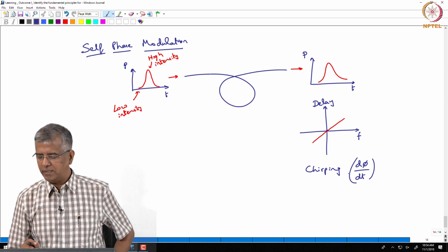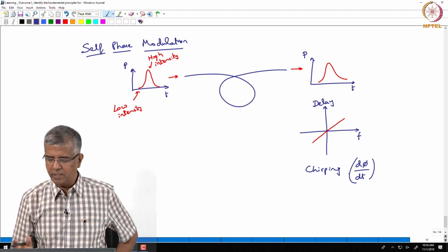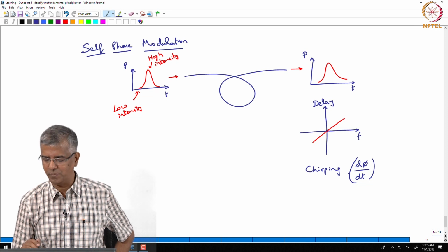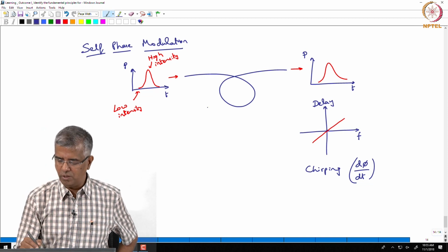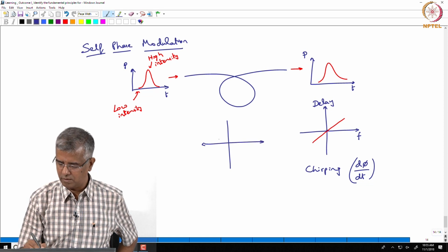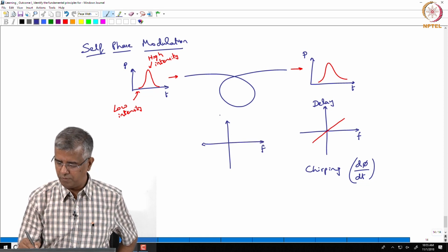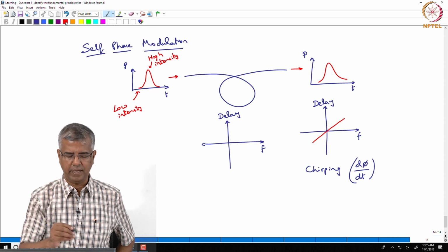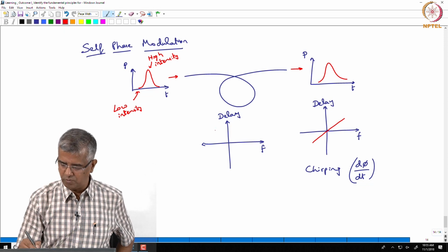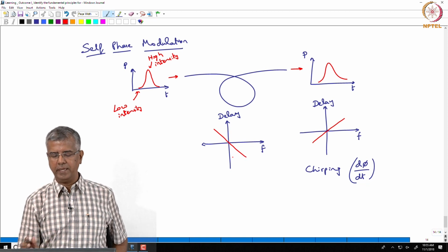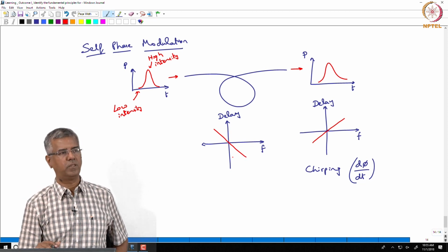The idea is, this chirping may not actually be bad from a communication perspective, because we know normally in communications we have frequency as a function of delay. You have what is called chromatic dispersion, right, and chromatic dispersion works out in such a way that the delay is like this with respect to frequencies.